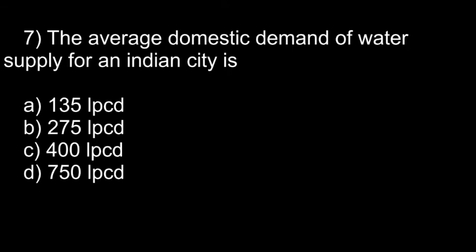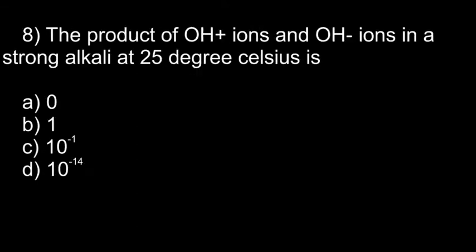Our domestic demand is 135 LPCD. For industrial purpose, it is 50 LPCD. For fire demand, commercial and institutional purpose, it is 20 LPCD. These are all about water demand, that is per capita demand. Okay. Now let's move to the next question.